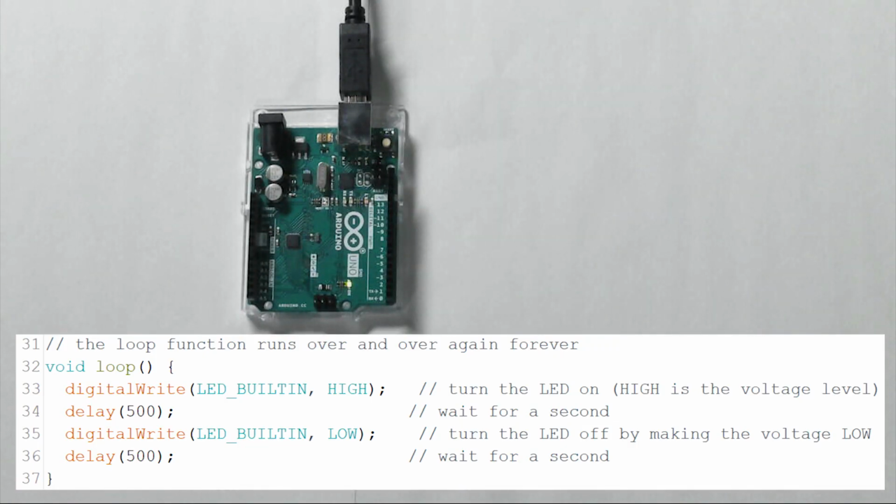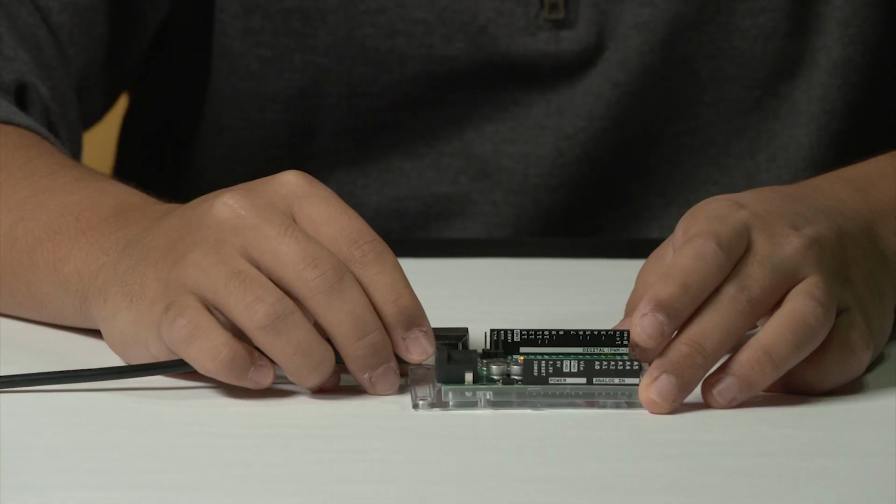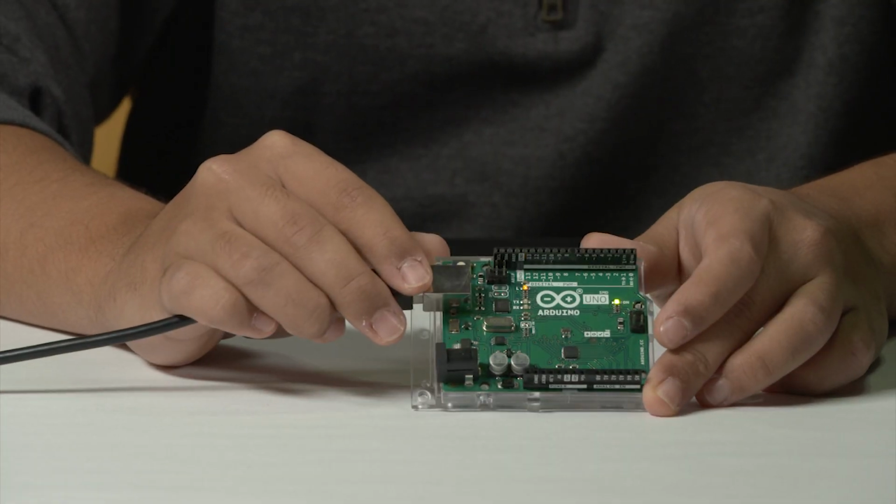Now we're going to go into the code, and on lines 34 and 36, we're going to change these delays from 1000 to 500, and we're going to see the effect that it has on the board. So we're going to change that and hit the upload button again. And now we can see that the LED is blinking twice as fast.